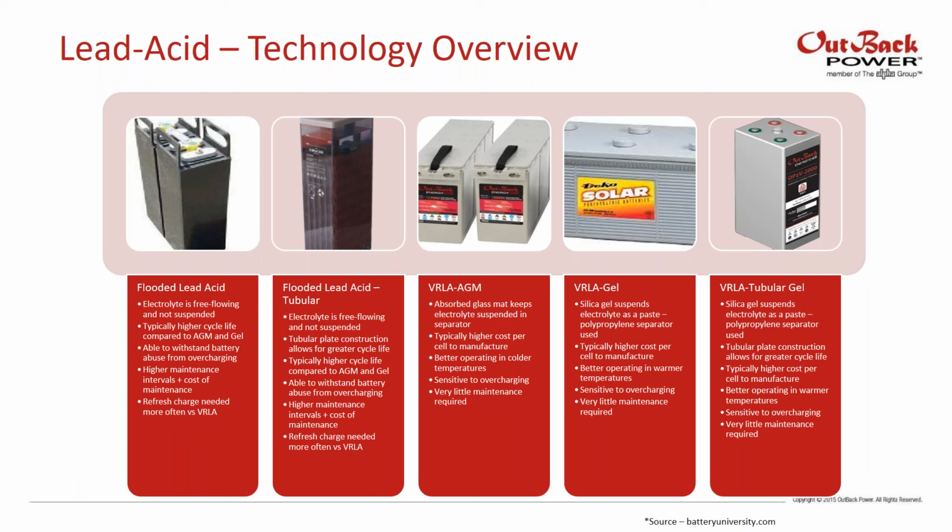Also, with lead being one of the heaviest elements in the world, these batteries are very heavy. They're hard to move around. It takes a little bit of willpower to move one from point A to point B. And then lastly, the capacity of the battery itself is significantly impacted by the discharge rate, or the current which you're drawing out of that battery, which is not necessarily true with other chemistries.